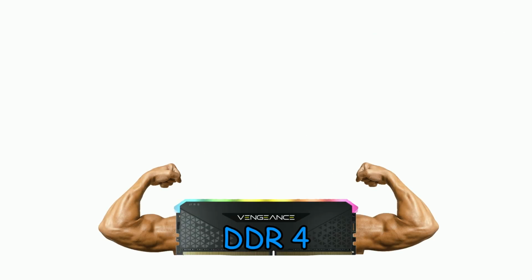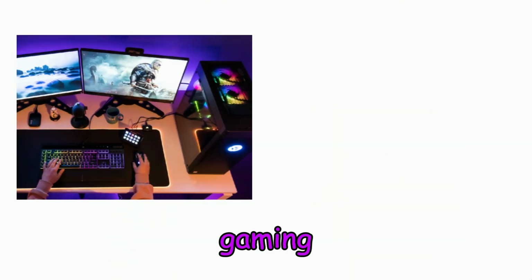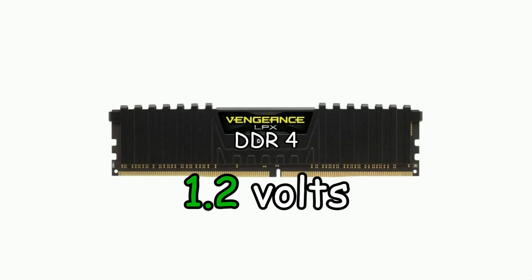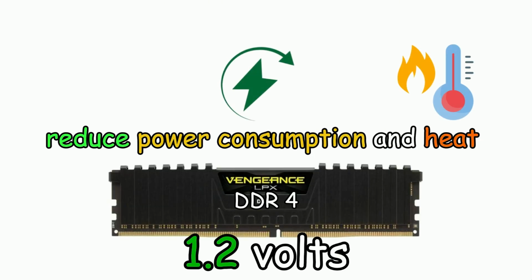This increase in bandwidth made DDR4 a better match for newer and faster processors, especially in systems designed for gaming, content creation, and other demanding workloads. Standard DDR4 generally operates at around 1.2 volts, compared with around 1.5 volts for standard DDR3. The lower voltage helped reduce power consumption and heat while maintaining higher performance.